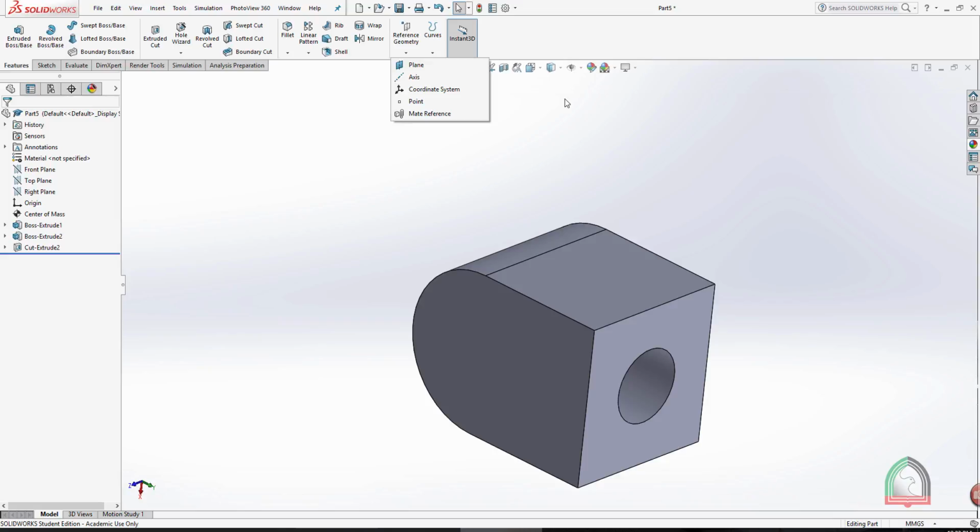If you know how to make a plane in a suitable or your required place, we can use that plane as a reference for your drawing, and we can make a 3D and assembly and everything over there. This is very useful at the time of 3D assembly, also in analysis. And we are going to discuss this in detail.